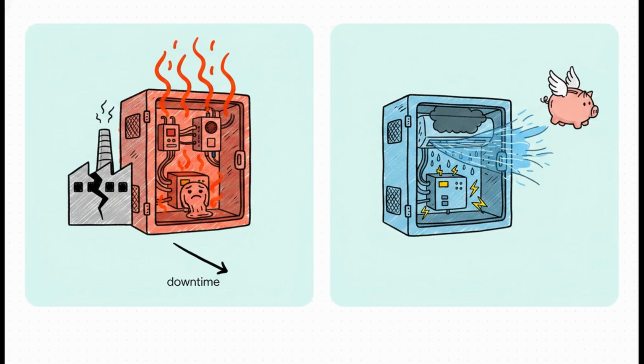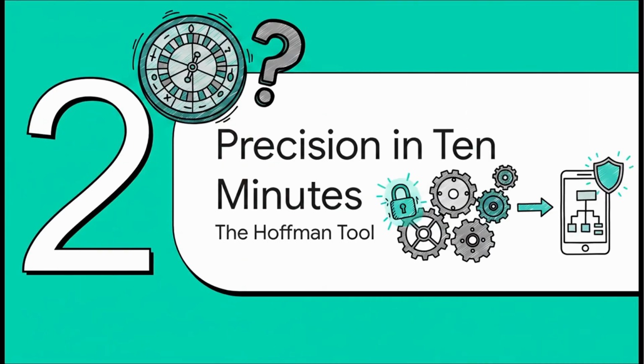If the cooling system is oversized, you may spend more than necessary on the unit itself and the energy required to run it. Oversizing can also create condensation, introducing moisture inside the enclosure and putting sensitive components at risk. In either case, guessing is a risk. And that is why a data-driven selection process really matters.